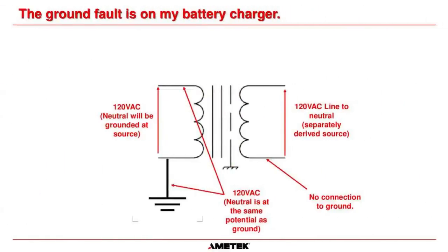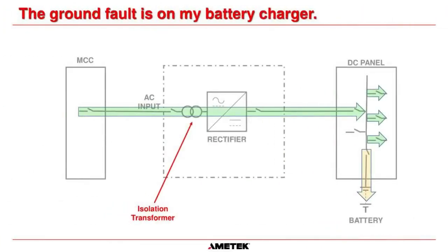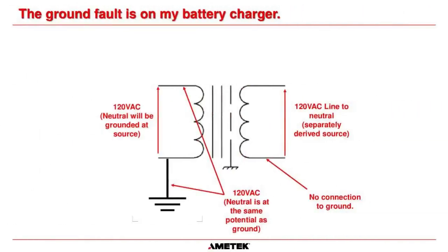So, as you can see in this slide here, we have an isolation transformer on the input to the rectifier. Okay. And that input transformer is very important. Now, I'm not going to look at a 3-phase system. We're just going to look at a single-phase system, so it gives you an easier understanding of what the transformer is doing. So if you had a charger that took 120 volts single phase into the input of the transformer, okay? So this top terminal here is the hot, and this bottom terminal here is the neutral.